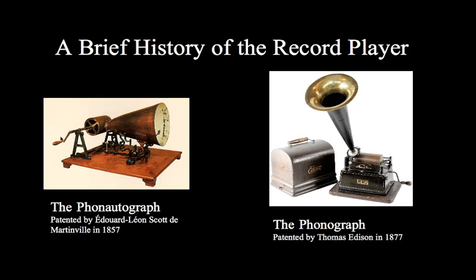So if I were to rotate the cylinder by hand and have you say something into the bullhorn, the vibrations on the drum that are connected to the needle that is being dragged across this cylinder will make the needle dig into the material on the cylinder, along with the wave or the vibration or the wiggles in the air as they hit that membrane, that drum down there at the bottom.